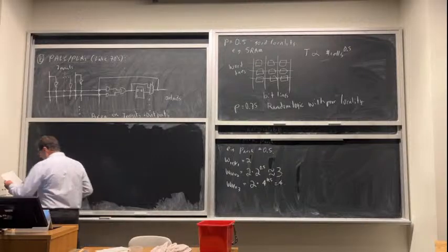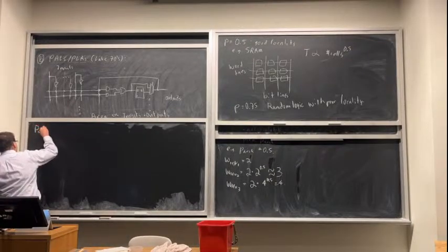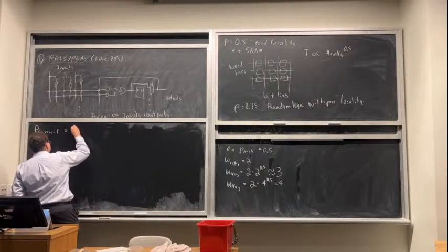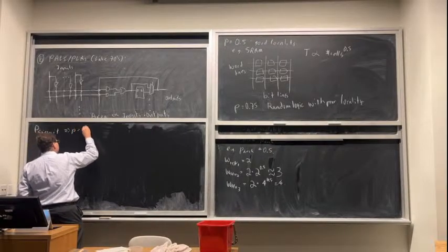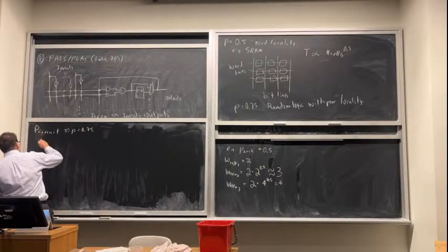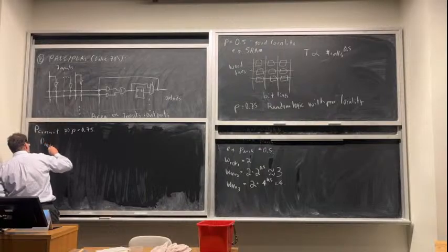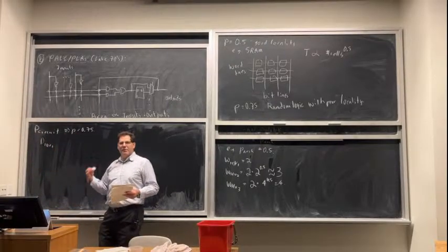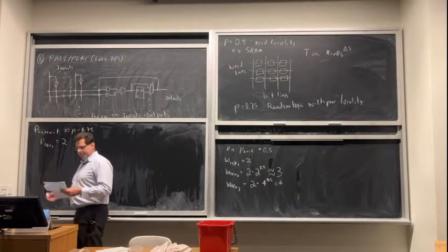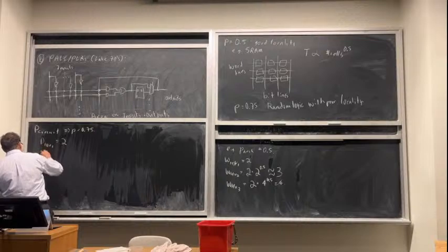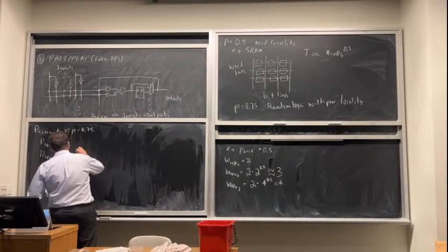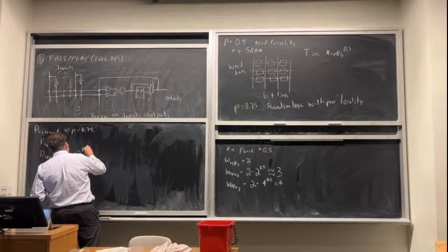But what if you can have random logic, for example control logic, that has higher exponents? Let's say p equals 0.75. There will be cases like that, though they're not going to be everything. So now we're going to write out not W, but demand. Instead of W, which is how many wires I build, we have the demand from this circuit. The demand at level 1 is going to be 2 wires. The demand at level 2 is going to be 2 wires times, I have twice as much stuff at level 2, my rent exponent is 0.75.